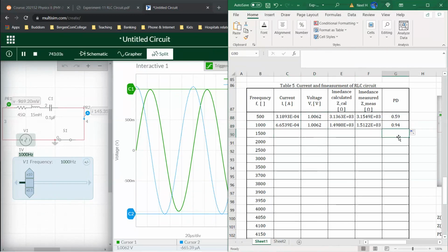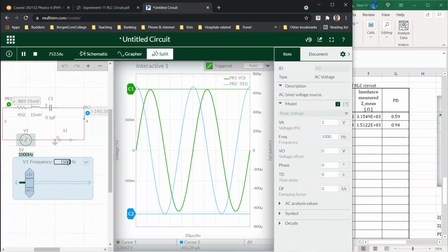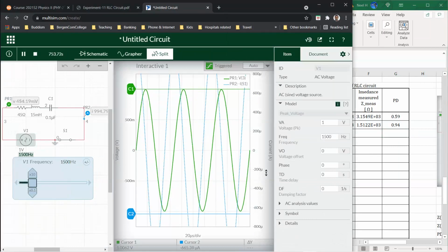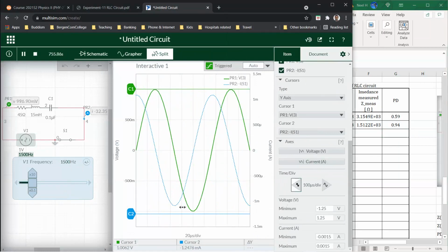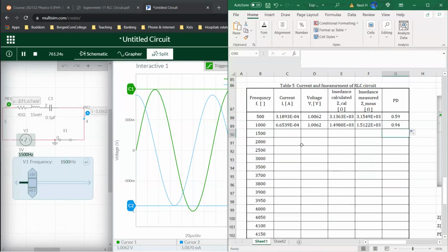That percentage difference number is so important, so carefully take a look, because if that shows something wrong, then we know something is wrong in our calculation, okay? And then that's it. It's very simple. We'll increase this 500 hertz at a time at this point. Voltage remaining the same. The current changes. Now it is in the milli range. It's increasing, right? So it is at 1.08 milli.